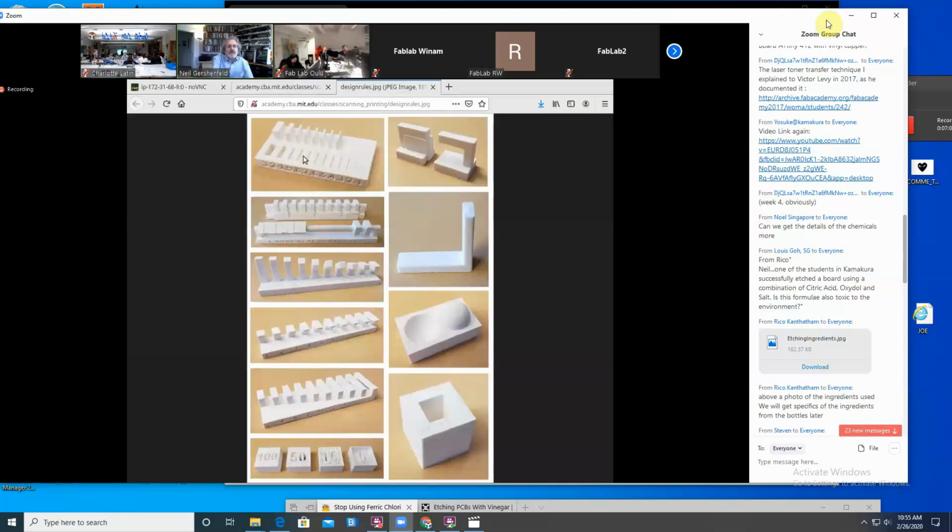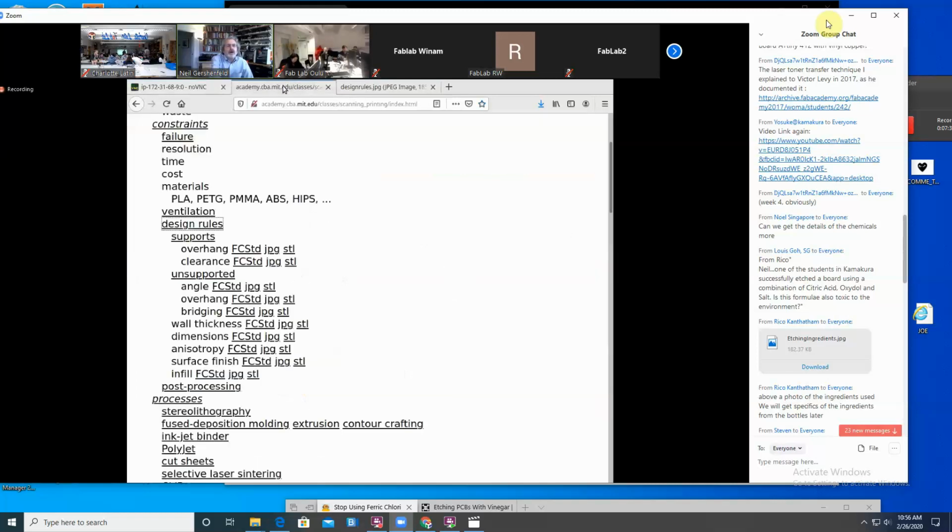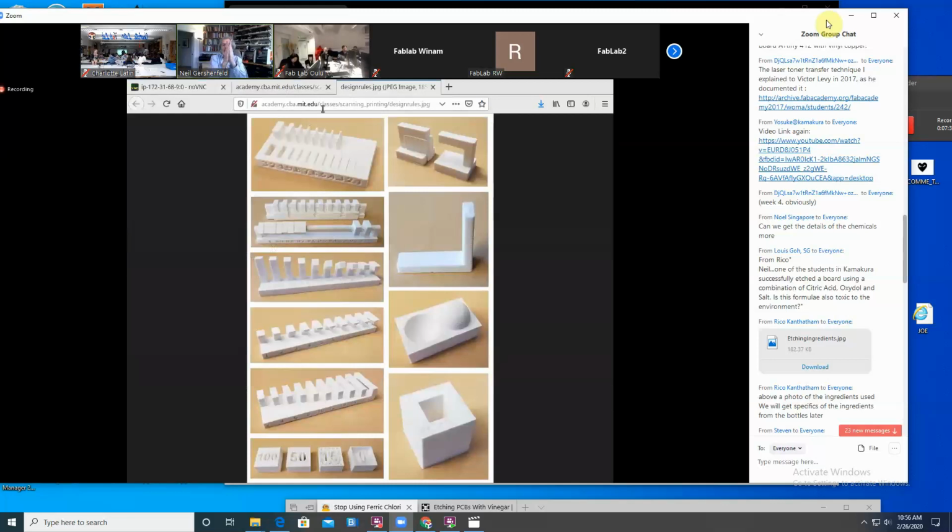So this first one is the thickness. I'll cover a number of processes; these apply to all of them. Here, this was done on an FDM printer. So the FDM printer lays down a pass of a filament, and the thinnest wall could be a single bead, but that has terrible structural integrity, then two, then three. So one design rule is how thin a wall can be before it falls apart.